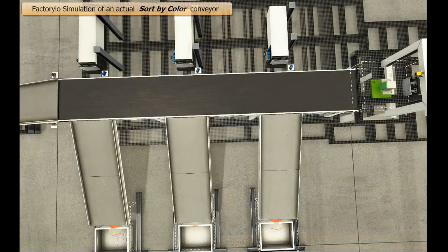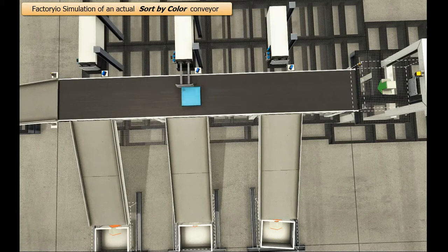You can see the target there was 112, and it actually stopped at 112, so it was pretty good there. Again, as you can see by the overhead view, the part stopped relatively in the same place. I turned off the indicator that shows where the part present switch is sensing, just to drive home the point that this is using the encoder.